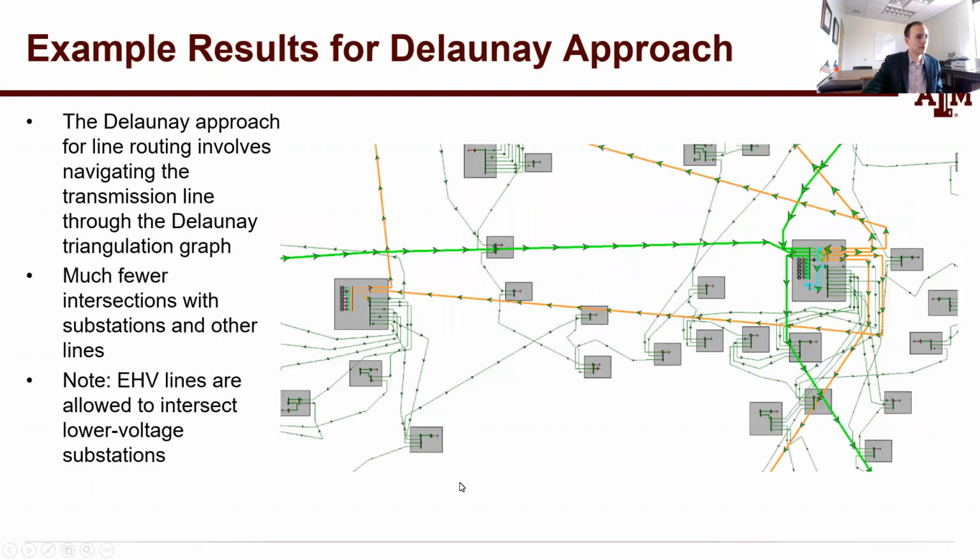So here would be an example of one right here where I've taken that previous one. This actually has the line flow arrows added in as well, but you can see that these lines have some bends added into them through an automatic algorithm that routes them around so that they're not overlapping lines, and you can see it a little bit more clearly where they're going. Notice that these large-scale EHV lines are not bending to wrap around every single little substation in between, and that's kind of a visualization decision made to try to keep these from being super windy.